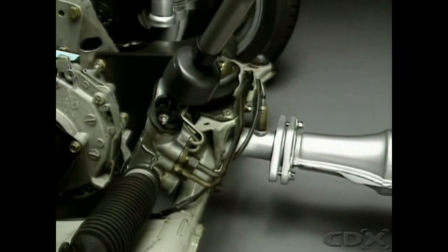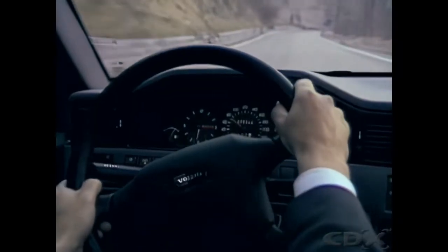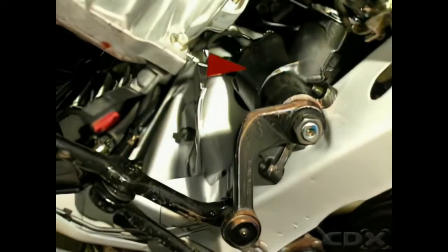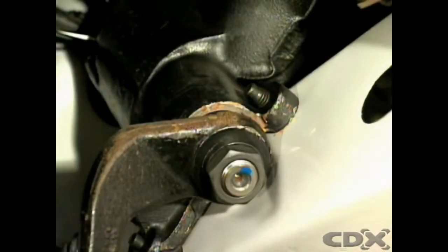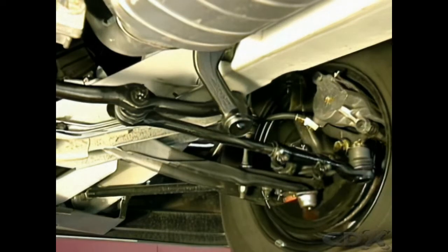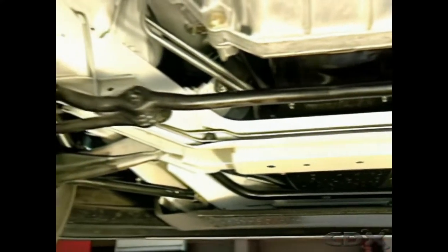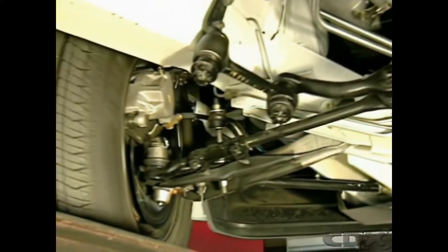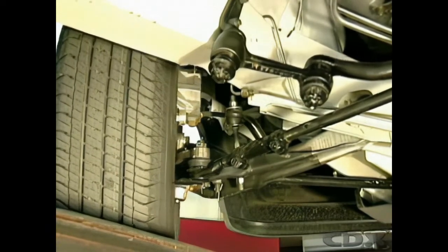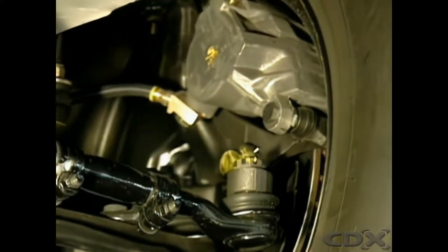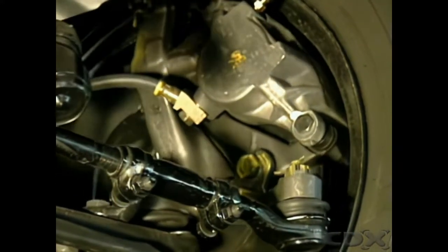The steering box converts the rotary motion of the steering wheel to the linear motion needed to steer the vehicle. It also gives the driver a mechanical advantage. The linear motion from the steering box is then transferred by tie rods to the steering arms at the front wheels. The tie rods have ball joints that allow steering movement and movement of the suspension. The steering arm ball joints are arranged so that movement in the suspension does not affect steering operation.